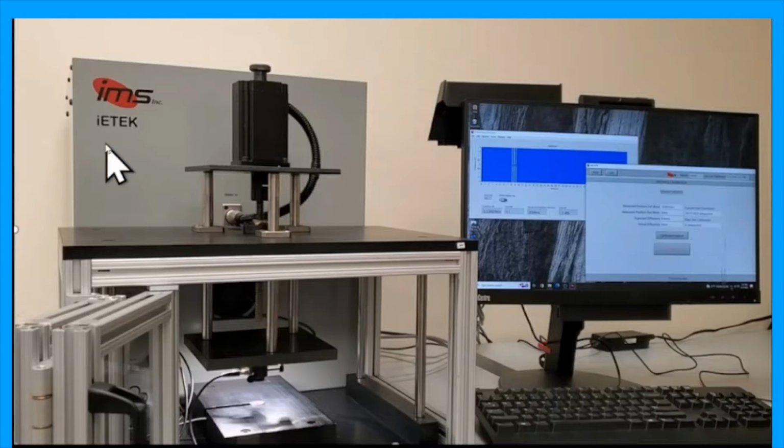Before I start talking about the calibration procedure, let me run down again, as I've done in some of the earlier videos, the basic components of the system. The gray enclosure contains the A to D conversion instrumentation, the ultrasonic pulsar and the receiver, the stepper motor drive and control, and the load cell signal conditioner. Other external components of the system are the stepper motor shown here, which is connected to a long lead screw, which goes down to a sensor platform. And the sensor platform contains the two sensors, the lower sensor and the upper sensor. And then we're now pointing at the user interface.